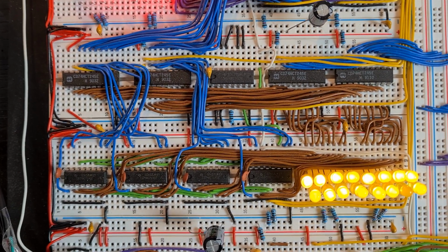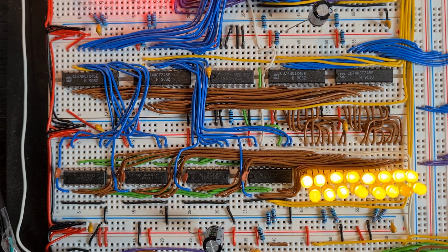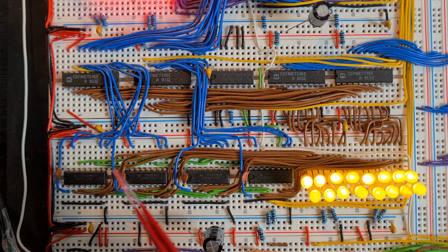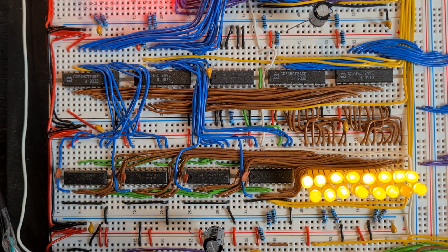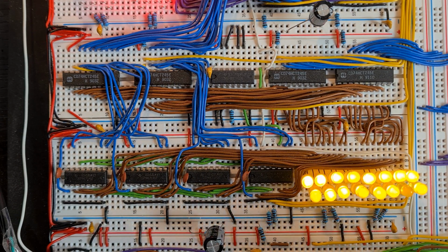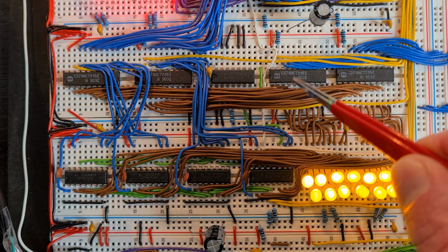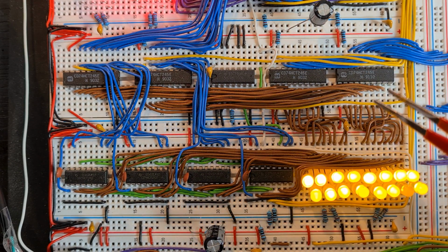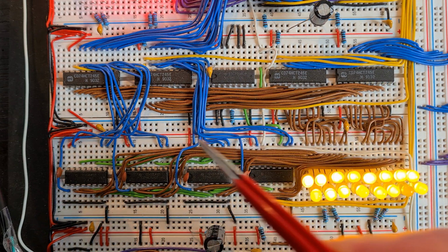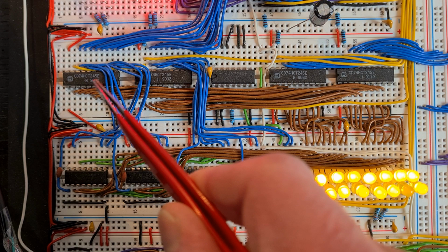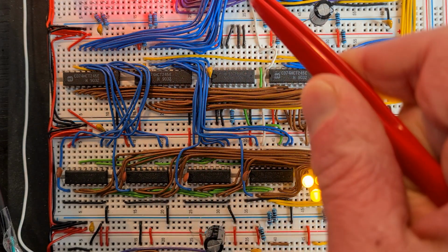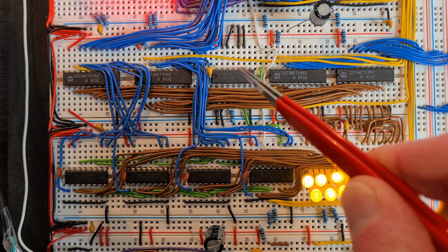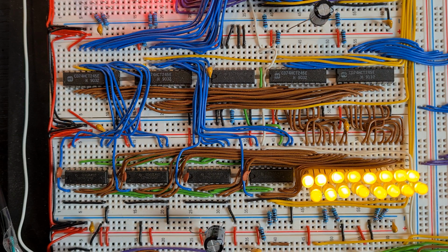This is the stack pointer. You can see the flashing yellow LEDs. This is the state, and these are the 4 counter chips that hold the current value of the stack pointer. The data bus is connected through these 2 bus transceivers with the stack register, and on the other side these 2 bus transceivers connect the stack pointer to the address bus. These are these blue lines that go up to the new register. And this is the NAND chip for the load line of the stack pointer.